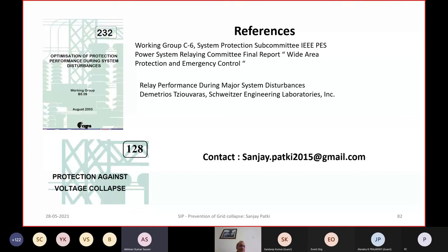Yeah, in this situation, actually, even for a single phase bank, restricted earth fault can be adopted. On the neutral busbar, you can have a CT connection outside the transformer, and you can have restricted earth fault protection with either the turret CT of the single phase on line side or an outside bay CT.